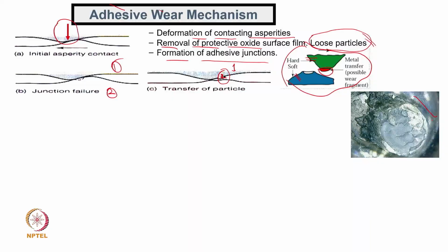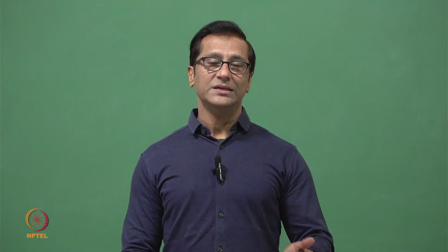And we are showing here one failed ball which we tested in a four-ball tester. You can see that the top surface, which was spherical, now shows a circular area instead of a point. Not only this, we can see some black color. That means material got displaced and melted, and finally got converted to solid again. So, material was displaced from here to there, was in a molten stage, and after some time it appears like this. The molten material solidified, and that is shown as black color.